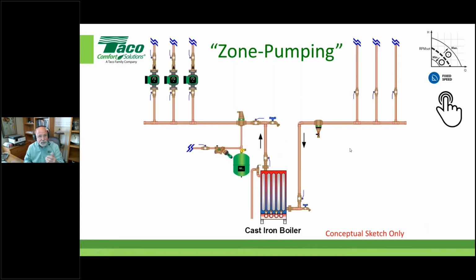For instance, you realize that with a zone circulator, when we're zone pumping something, there's nothing downstream of that that's going to change automatically. There are no zone valves or diverting valves typically or anything like that. So that circulator is a delta P, as in pressure, circulator.